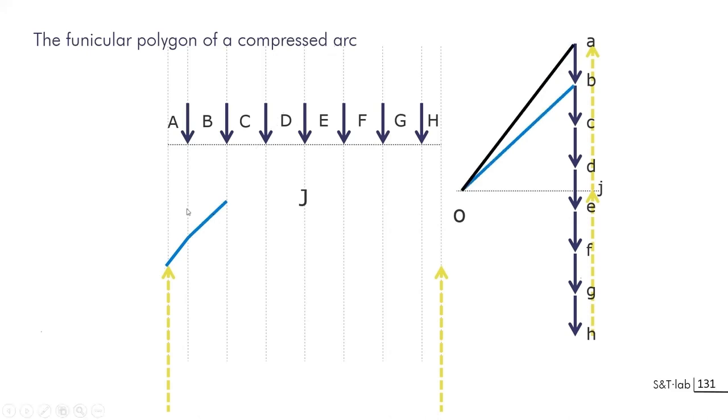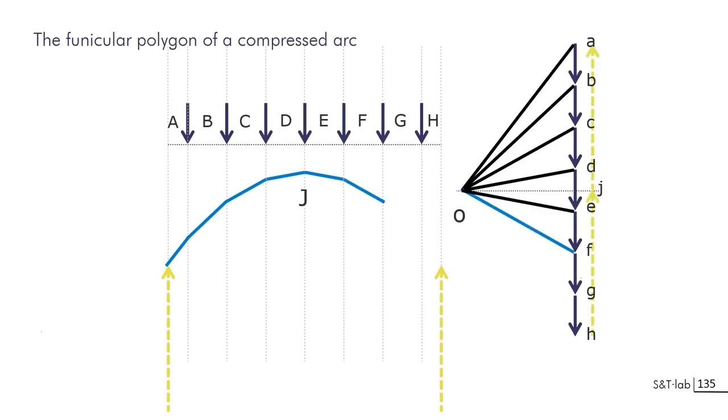The fact is that as soon as you have three lines, you have your first triangle of forces here, showing that this loading will be equilibrated by two segments of line, two parts of the arch, and you will get the resulting force from this. So you will have a means to draw this funicular polygon very easily, and this will provide you the form of the arch. So this is about design, this is about form finding.